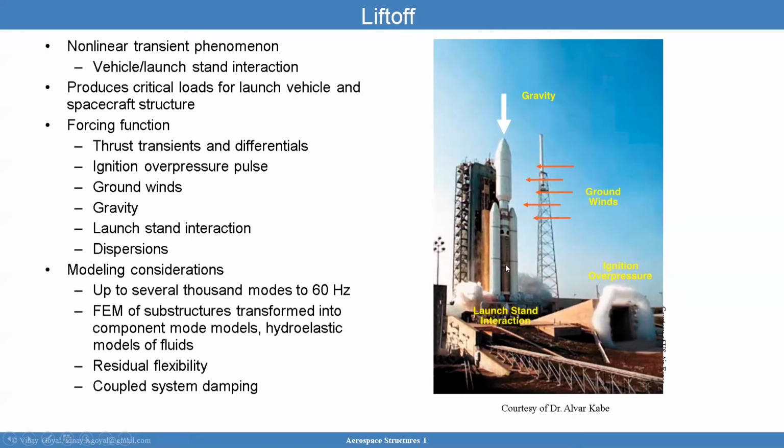Gravity is a major component there. Launch stand interaction, which I just talked about, and dispersions. Modeling consideration is that you want a model that can get up to 60 hertz of data, and the finite element of the substructures have to be transformed into component mode models. You also want to have hydroelastic models of the fluid because everything is full of fluids like stage tanks and things like that. And you also need a coupled system damping as you go through this analysis.